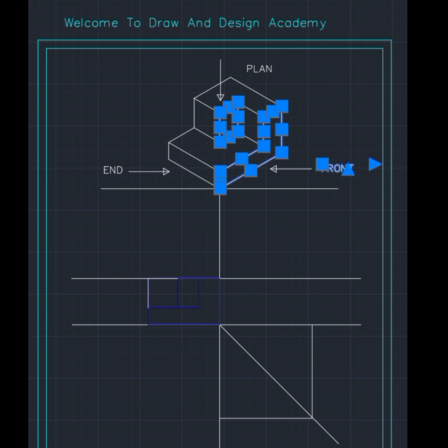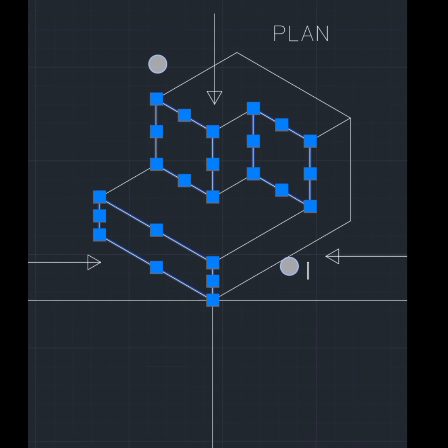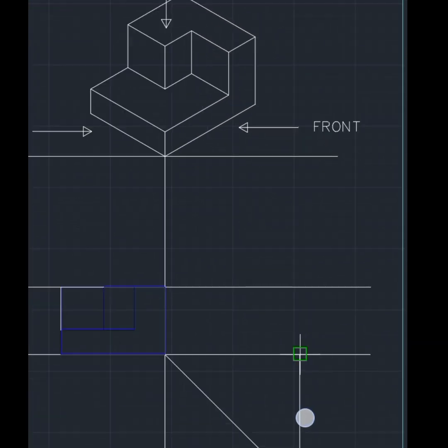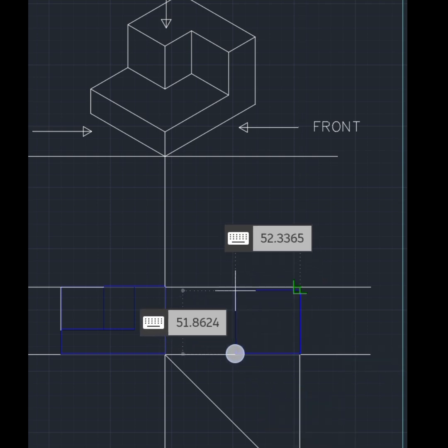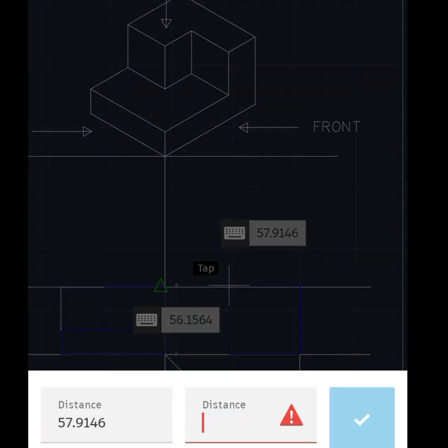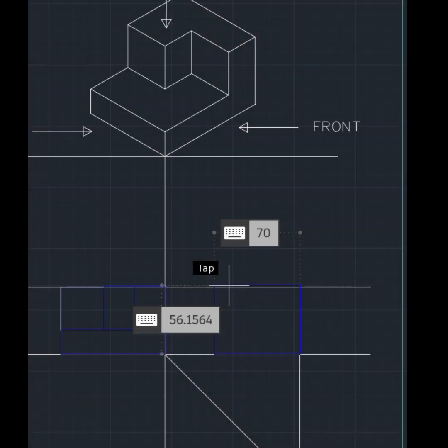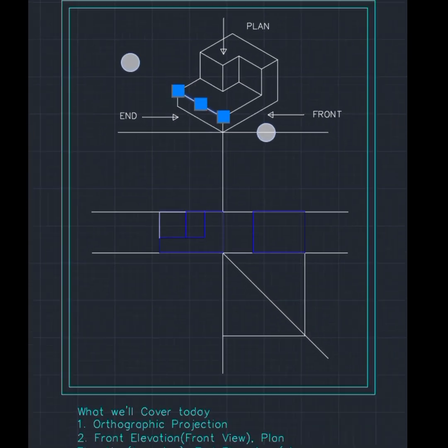So next up, we're going to draw the end view, that is the side view, this one here. So how do we do that? Click on draw, click on rectangle, then you drag it out, you input the given dimension. Let's take our length as 55 and our breadth as 70. Click on the blue tick and we're cutting a rectangle, so that's the line we want to offset.